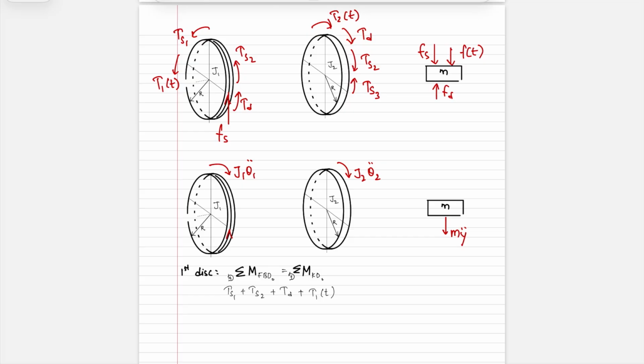So now this moment will be r cross F. You have your palm aligned along r such that you can rotate your hand towards the direction of the force, which will result in a direction like this, the same direction as what has been shown here. So this will be plus r Fs.